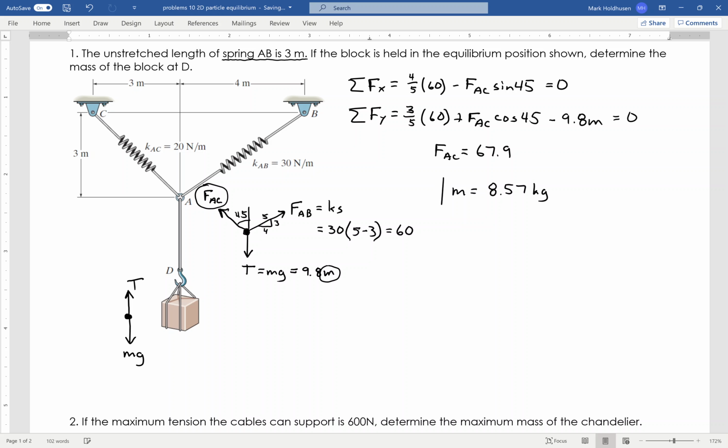So again, draw a free body diagram where you put all the directions, everything you know about the forces, angles, magnitudes, things of that nature. Once you have that drawn, then it's very easy to sum the forces in the horizontal x direction, sum the forces in the vertical y direction, set them equal to 0, and then solve up to two unknowns, looking for the answer that we get.